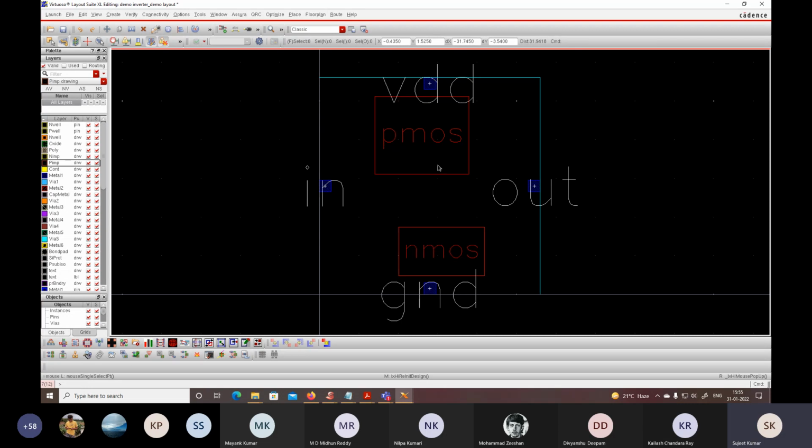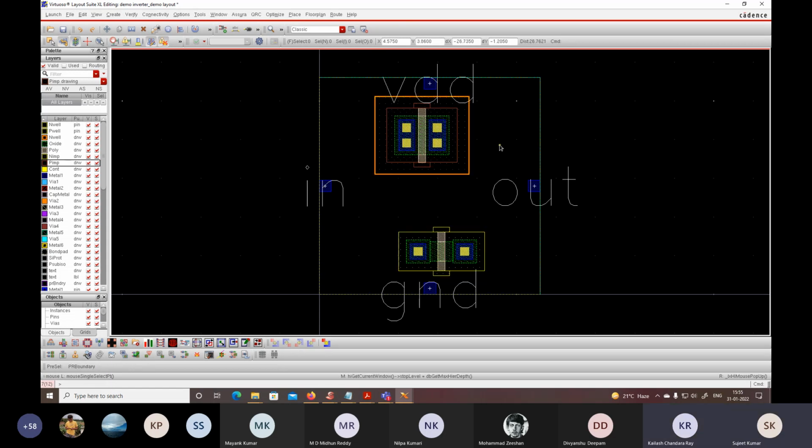So the PMOS cell and NMOS cell have their layout model in the library already given. For this, you can press Shift F so that it can access the original layers of the PMOS and NMOS. So now we have to connect all these layers to layers and design one layout here. So this is the PMOS and this is NMOS. According to our schematic, we have to connect.